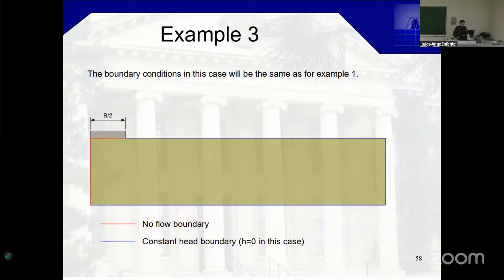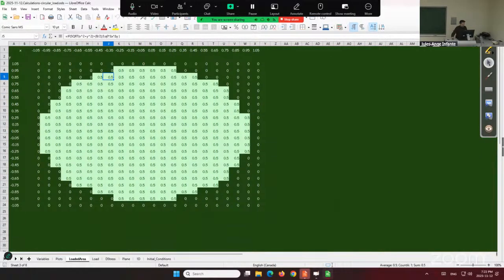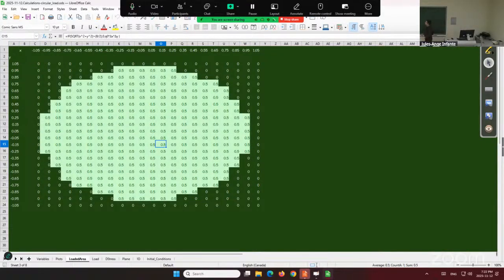So we had been working on our spreadsheet. Right, so if you go over what we did, we did the calculation of the stresses. I had set up a load, and here you notice that it's offset by half the interval. The interval was 0.1, but I offset the coordinates here because I'm replacing the stress by a concentrated load at the center.